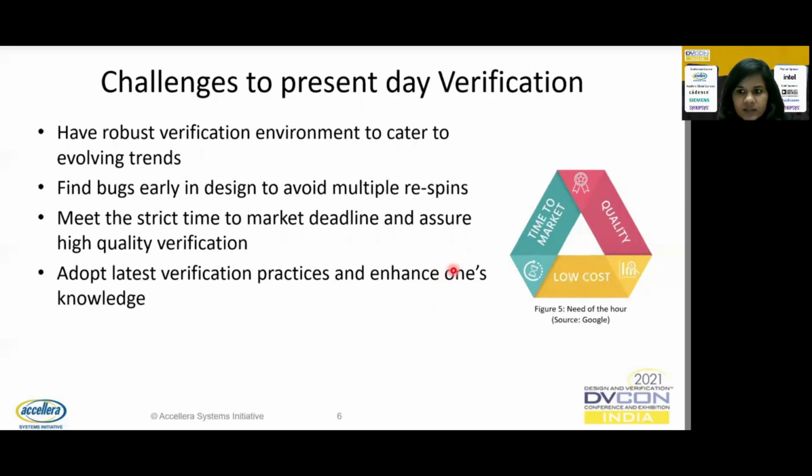To us, this threat to signal integrity during the verification of DDR5 seemed like a warning bell. It became imperative for us to find a way to stress test our PHY, which led to the development of our in-house channel model, supplemented by our alignment checkers. Today, we can confidently support the industry solutions with lowered chances of unwelcome surprises in the post-silicon stage.